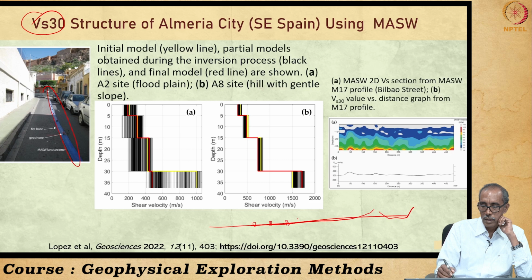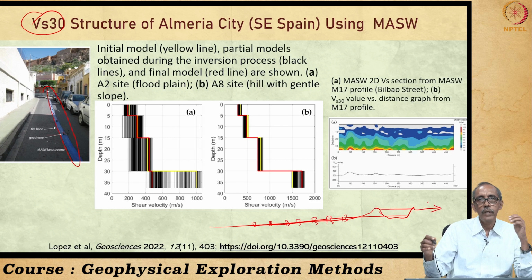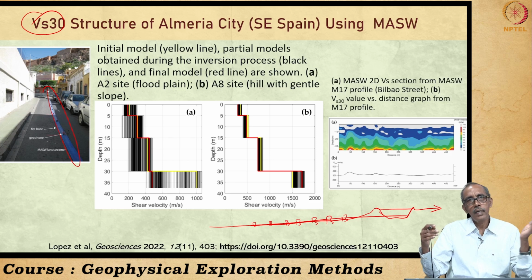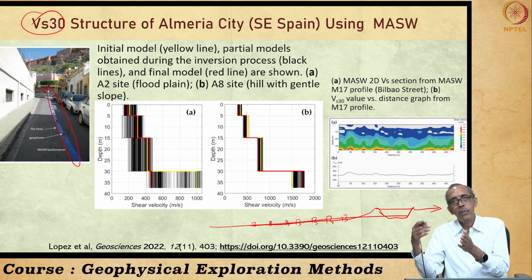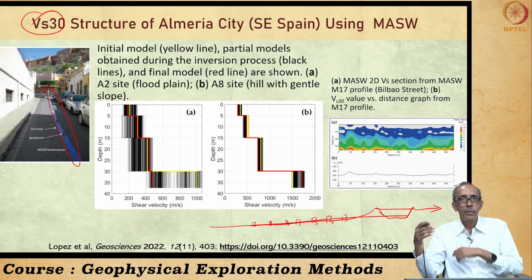These are all the receivers which are called hydrophones in the case of an ocean survey. The ship is continuously moving, we keep on repeating our survey. So, the entire profile is continuously studied, several kilometers are continuously studied, because we will be using some energy source, usually air guns. Air gun will fire, work will be over. The ship would have moved, next, like that we will progress.